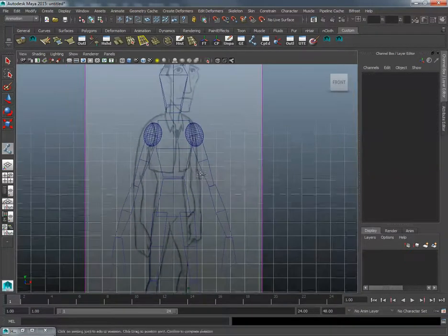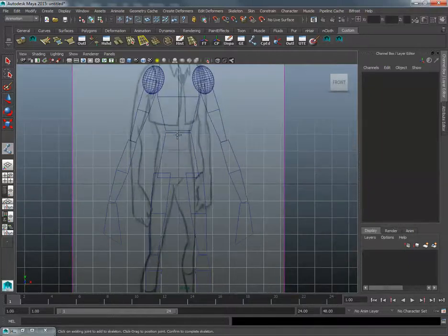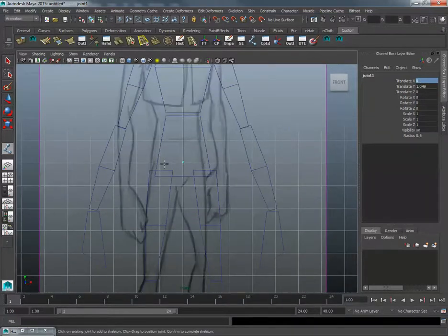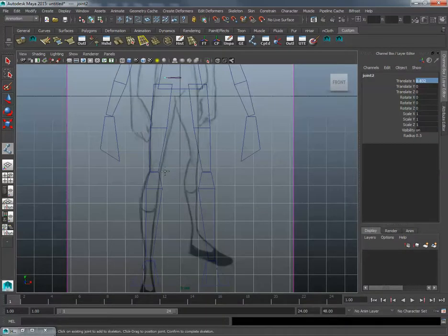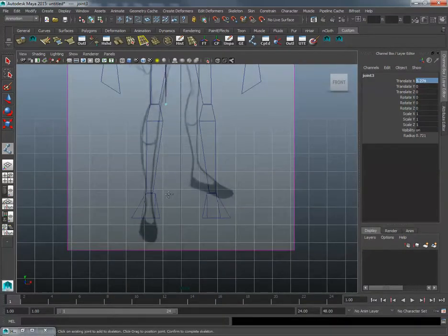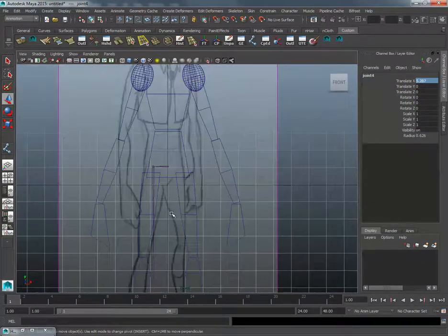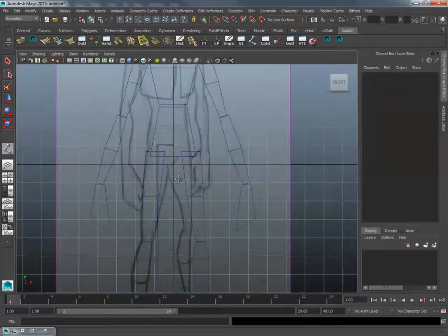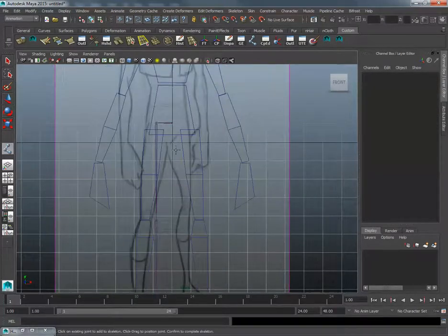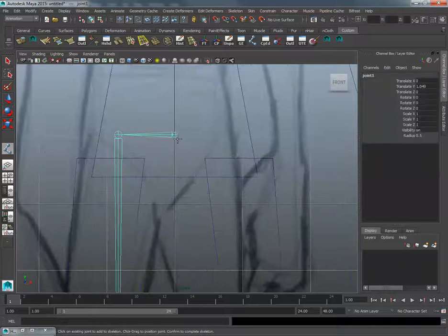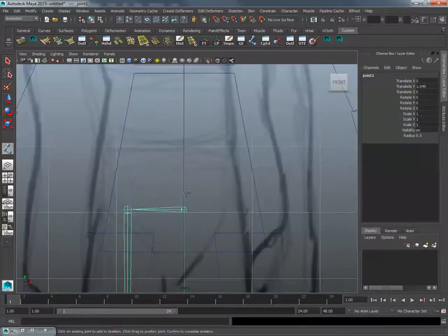Click on the skeleton tool, and I'm going to just create a basic skeleton. It's not going to be particularly complex. So just going to go ahead, holding down shift so I can get straight skeleton bones. I'm going to just create all the parts that I need, which is, that's the leg. I've deliberately made the foot longer, as you've got to treat that as if it's pointing down. When you finish doing a bone chain, press Enter. Press G to go back to your original. Go back to the original bone and click on it. Now you can start creating other bones springing off from that as well.